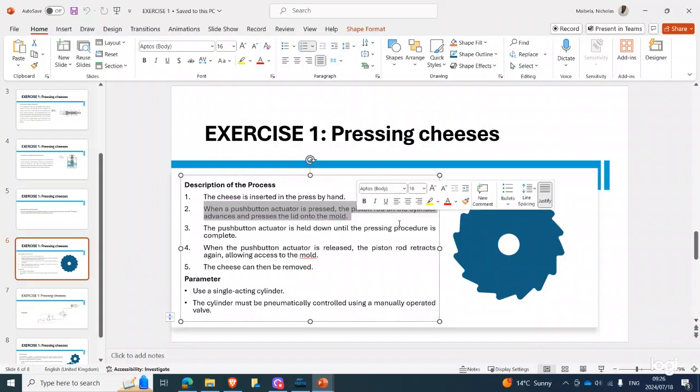This statement should tell you that the actuator, which is the cylinder, has its initial position at the back end, or retracted position, and at the point where you press the push button, that's when the cylinder is supposed to advance. So that should tell you that you're supposed to use a normally closed three-way valve.